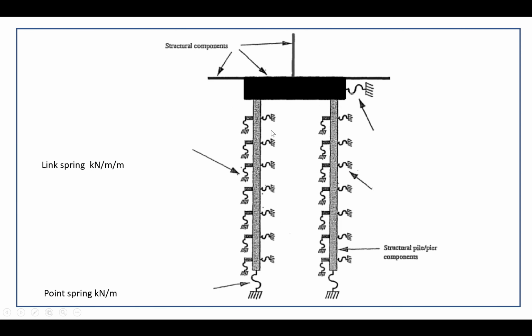Now let's come back, and this schematic is the same, and we want to focus on the formula. You see here I highlight different colors to illustrate the skin friction. So you can calculate skin friction by using the formula 40 multiplied by SF and multiplied by the allowable soil bearing capacity.